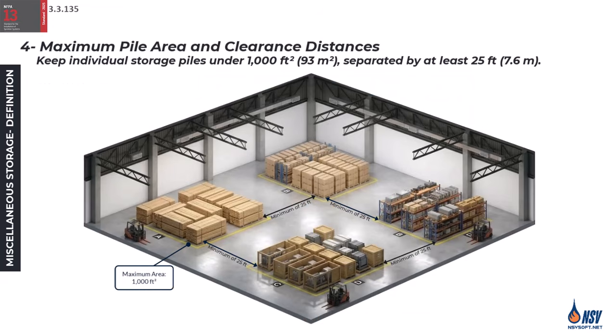And fourth, our individual storage piles cannot exceed 1,000 square feet, and we must separate each storage pile from the others by a distance of at least 25 feet. This rule is designed to act as a built-in fire break.